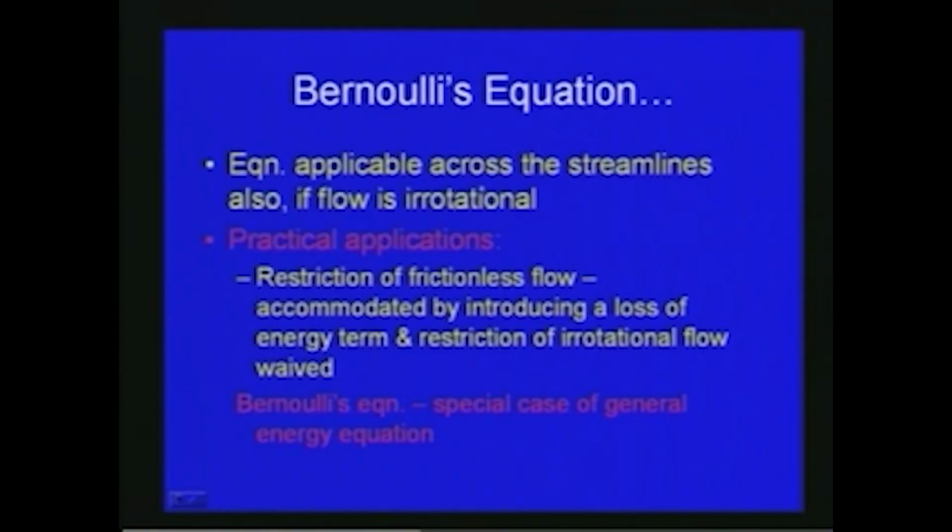And in some practical applications, if the restriction of frictionless flow can be considered, we can accommodate it by introducing a loss of energy term, and the restriction of irrotational flow as we have seen here. We can apply this to many cases which we will be discussing later. Some important applications of Bernoulli's equation we will discuss later. Bernoulli's equation, as we have seen, is a special case of the general energy equation.